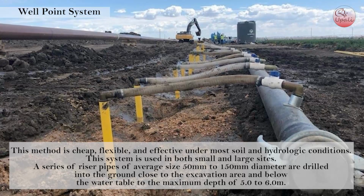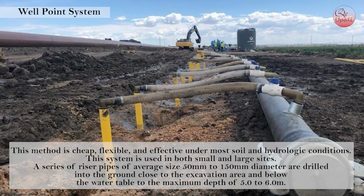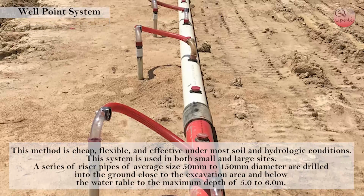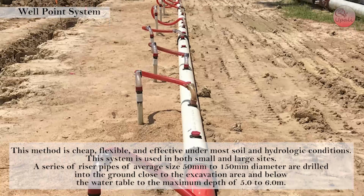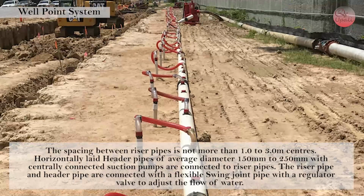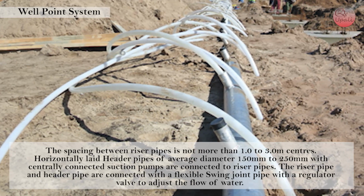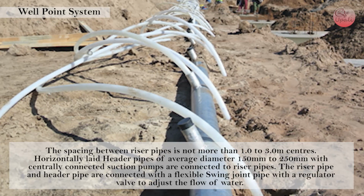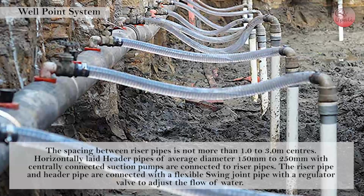A series of riser pipes of average size 50 mm to 150 mm diameter are drilled into the ground close to the excavation area and below the water table at the maximum depth of 5 to 6 meters. The spacing between riser pipes is not more than 1 to 3 meter centers. Horizontally laid pipes of average diameter 150 mm to 250 mm with centrally connected suction pumps are connected to riser pipes.